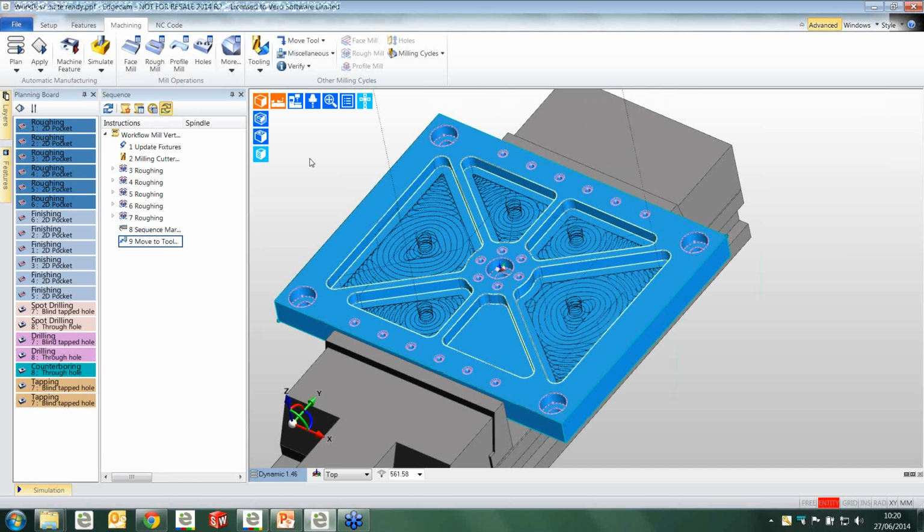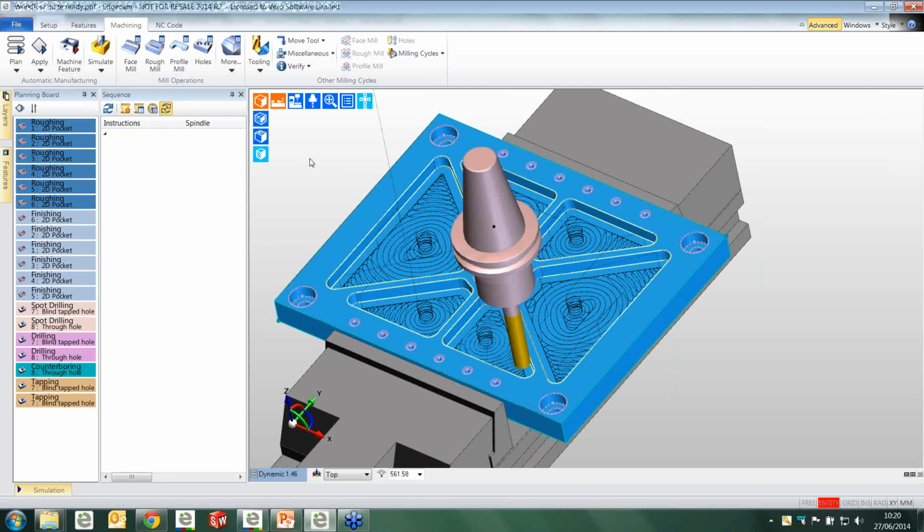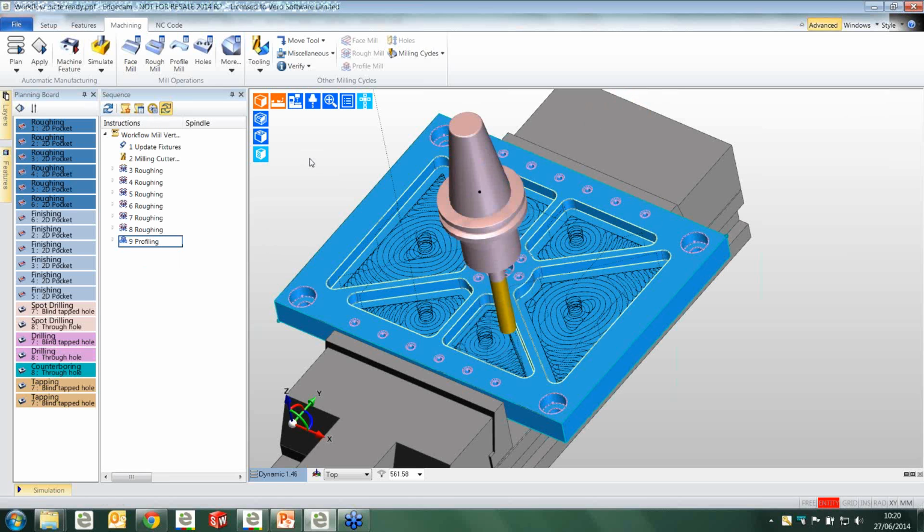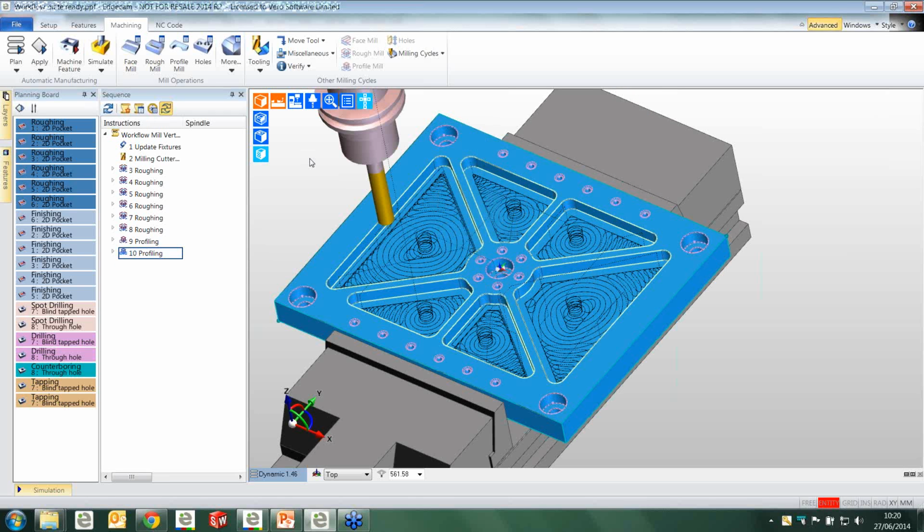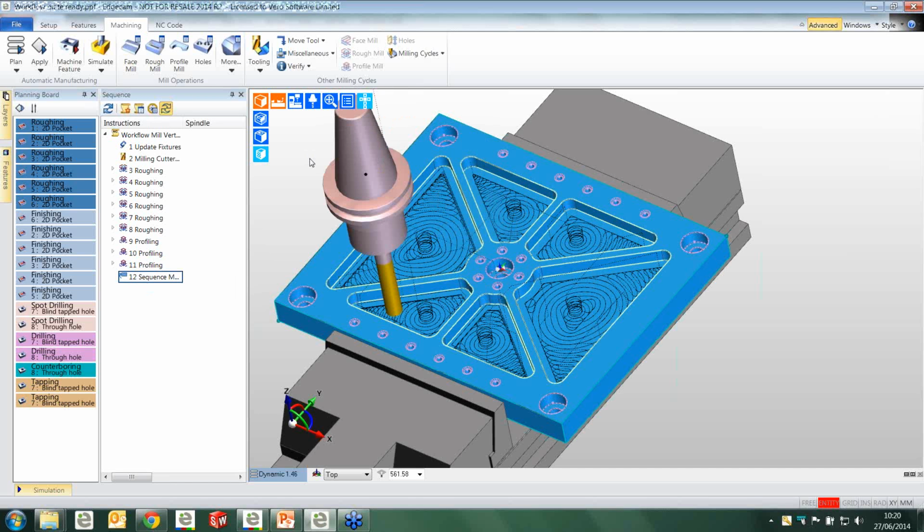So you can see there that we're using the same tool, moving around the different pockets. As I've said before, you can influence this. We maybe want to pick a bigger tool and come back with a smaller tool and rest machine the pockets. I've elected to use one tool to rough the parts complete because I'm using waveform. It's a very fast, effective, high-speed roughing strategy inside Edgecam.